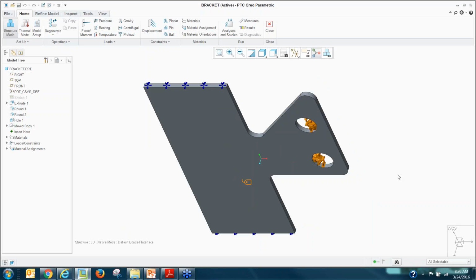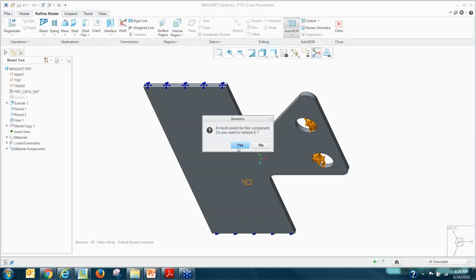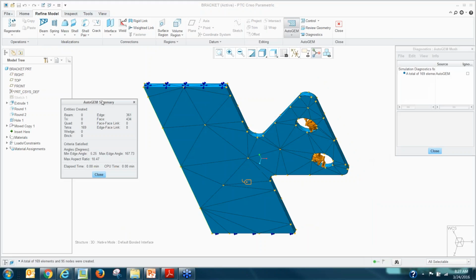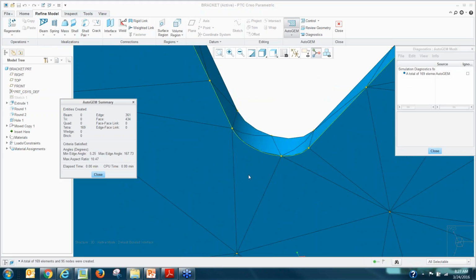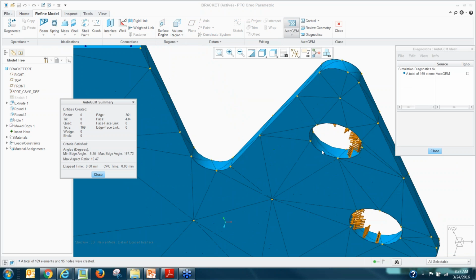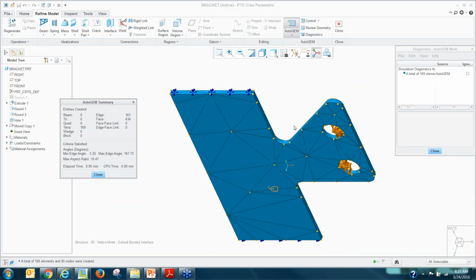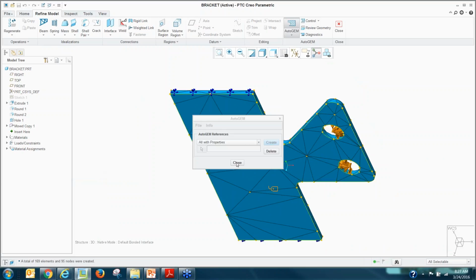Now, remember, as I was talking about that technology where it automatically creates the mesh and elevates the polynomial, I don't even have to really create the mesh. I mean, if I have to look at the mesh, I can, right? I can say, let me just create the mesh, and it will create the mesh for you. You can see it creates a tetrahedron mesh, and you might be surprised as to how big of an element it's creating around the holes and curved geometry. It is not refining it in here. The reason is it goes to a 9th-order polynomial automatically, right?